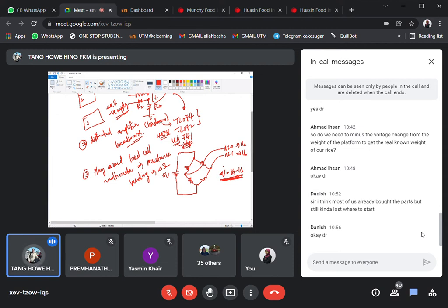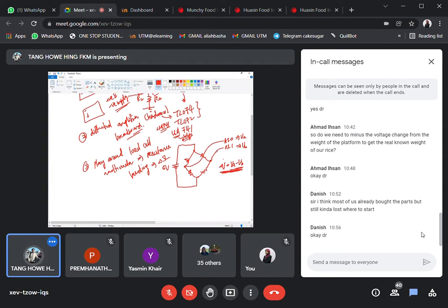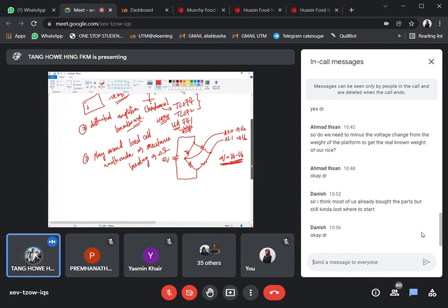So this is playing around with the load cell, just for you to get familiarized with what this load cell is about. Okay, so the fourth step will be you integrate your load cell with this differential amplifier. In that case, you just measure the voltage output from this differential amplifier, because the differential amplifier will be amplifying the signal.